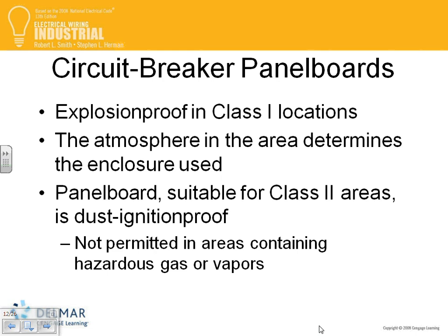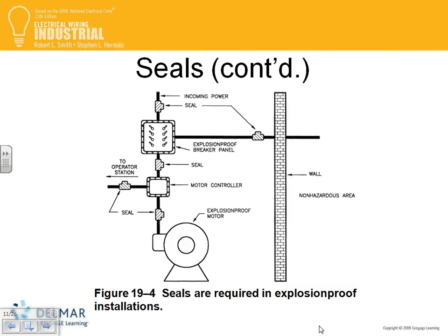Okay, circuit breakers and panels. If you want to talk about expensive equipment, imagine an explosion-proof breaker panel. You're talking about 5 to 10 times more. If it's a 100 amp that costs you $100, multiply this by 5 to 10, a $1,000 piece of equipment. So equipment becomes expensive, bulkier, hard to work with. If you're bidding a job that's hazardous location Class 1 Div 1 versus non-hazardous location, your multiplier, depending on the type and all the stuff, is almost 5 times more. It's going to cost you labor and material to work with this equipment. So that's why we care about these places, guys.